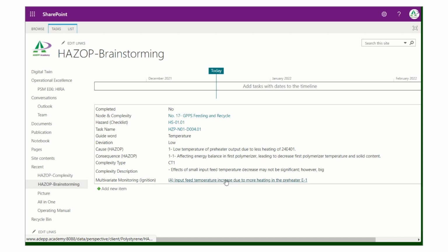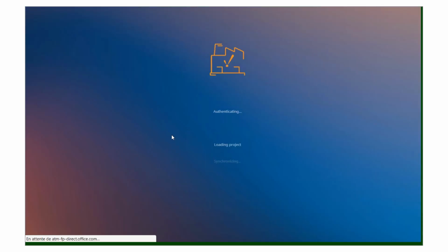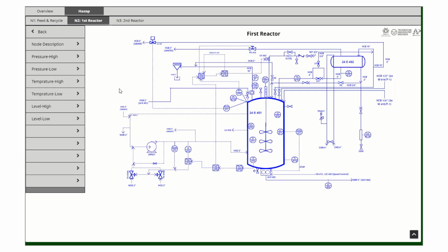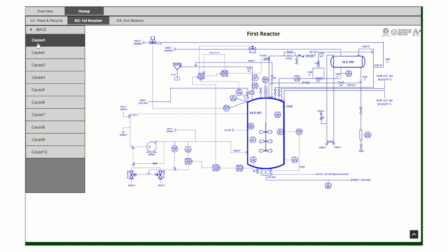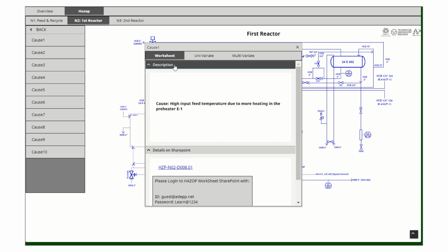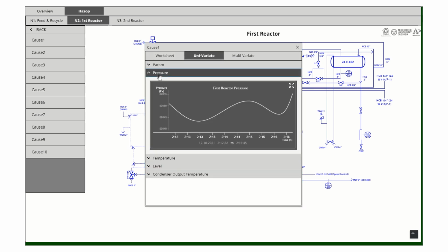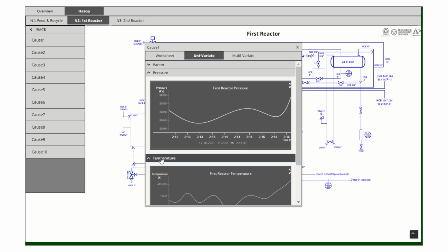This page is a web-based SCADA HMI interface, and therefore the HAZOP team or operator can interact with the simulation and observe the results of the cases that they are testing. For example, they can open and close valves or start and stop pumps and observe the behavior of the whole process immediately.